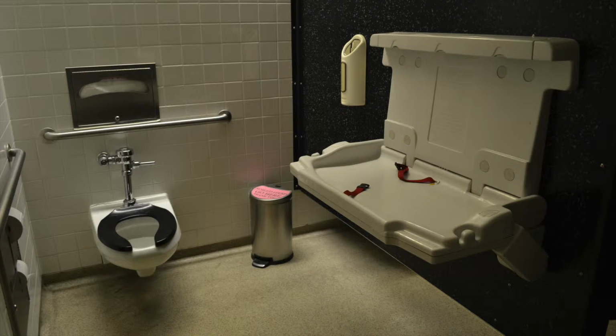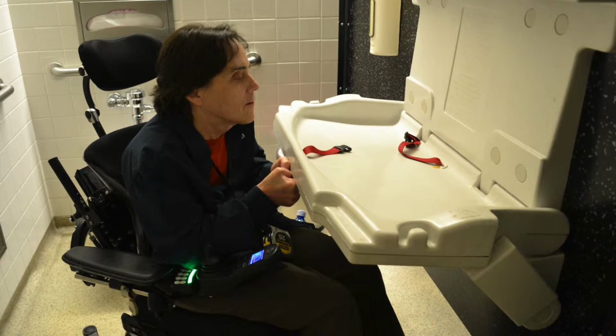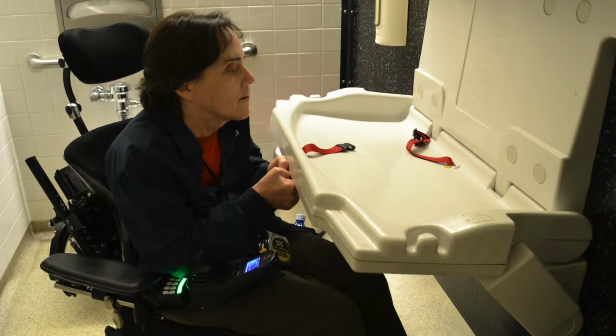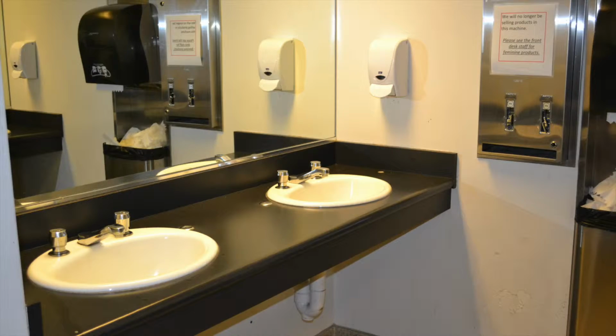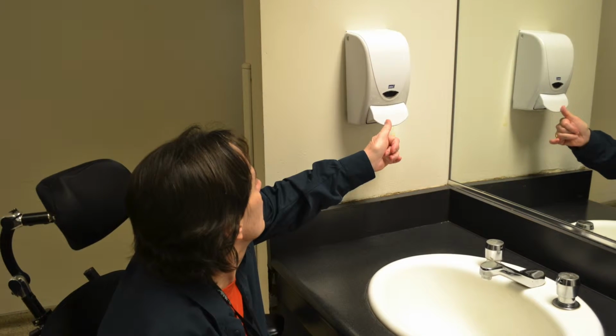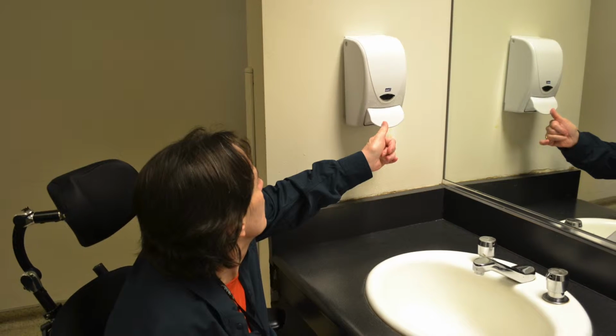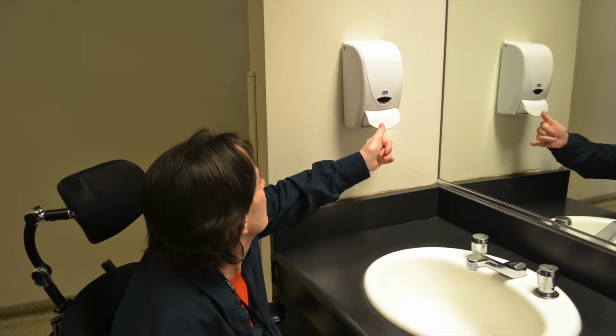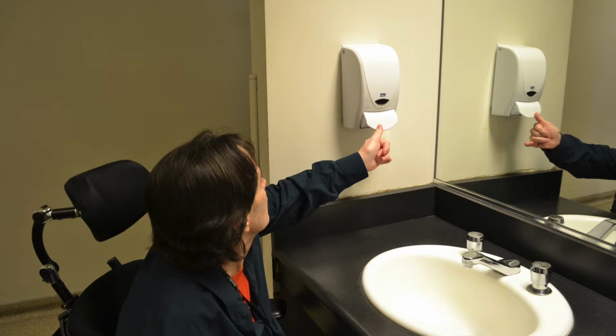Baby changing tables inside an accessible stall can limit the clear space if someone in a wheelchair is unable to lift it back into place. When it comes to countertops and access to everything from soap dispensers to paper towels, reach ranges must comply with the 2010 ADA Standards for Accessible Design. Reach ranges are from 48 maximum to a minimum of 15 inches off the floor, although 42 inches is preferable, especially when reaching over a counter.